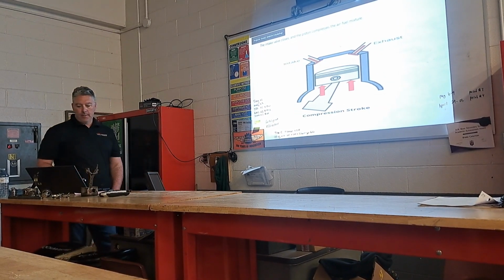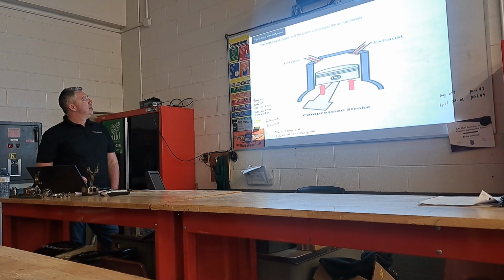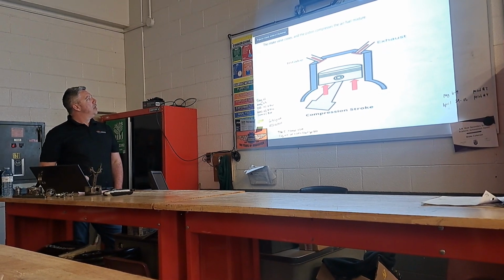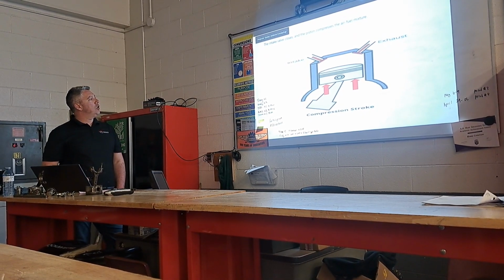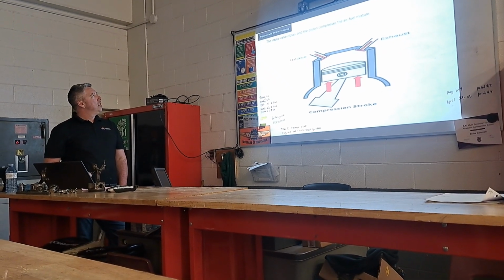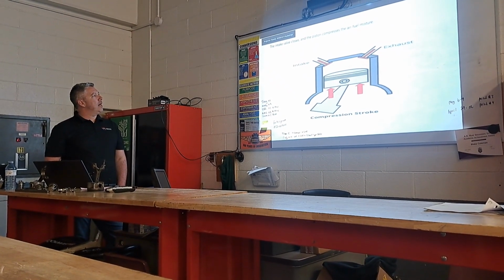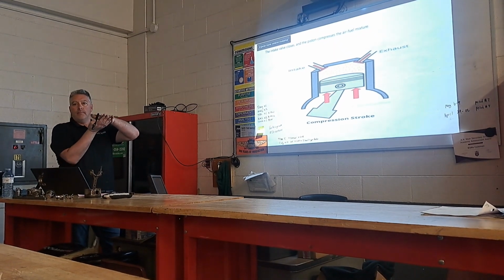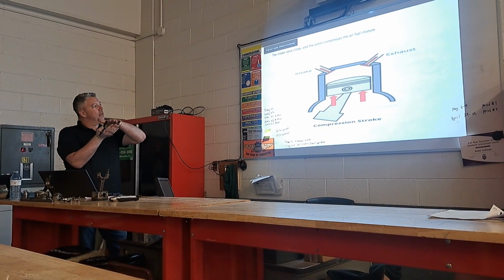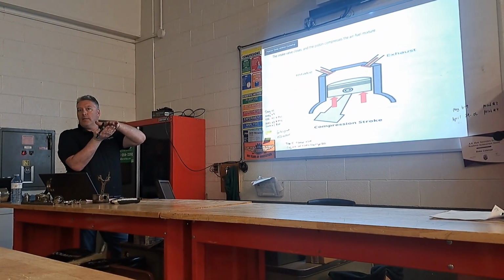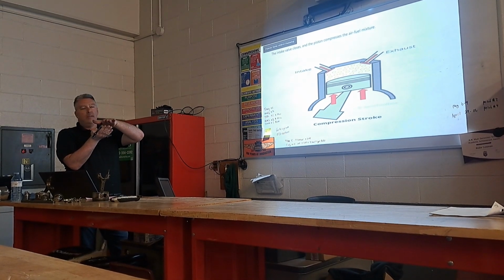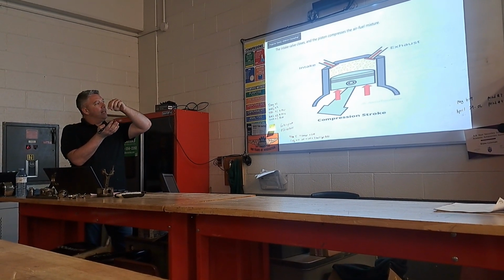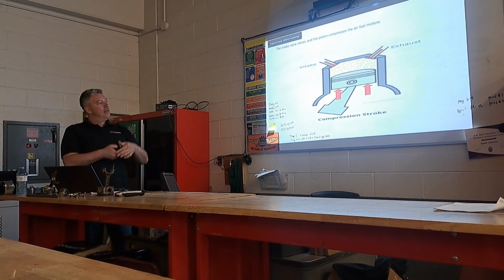Next, we have the compression stroke. The intake valve will be closed. Both valves are closed, and the piston compresses the air and fuel mixture. So the piston's coming up now, compressing all the air and fuel. And when you compress vapor or liquid, it gets very hot. Very, very hot. All you need now is a spark to ignite it.